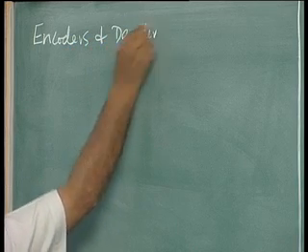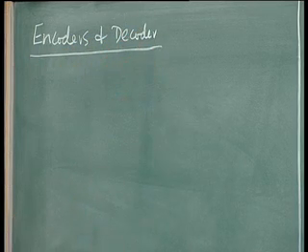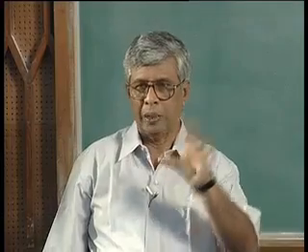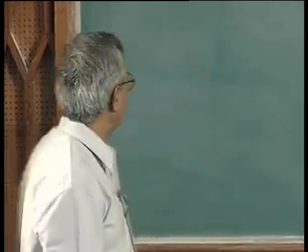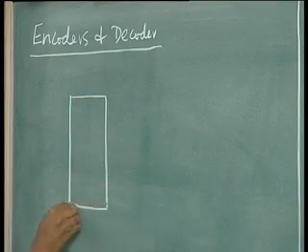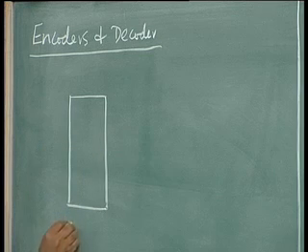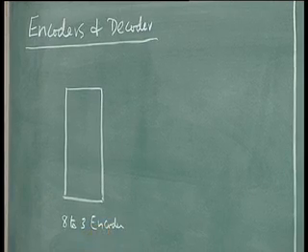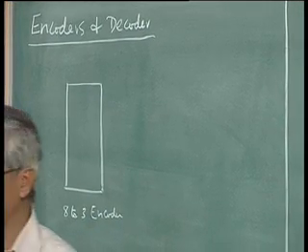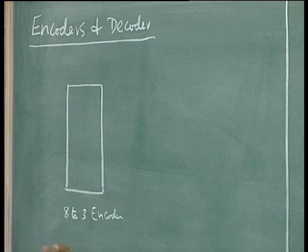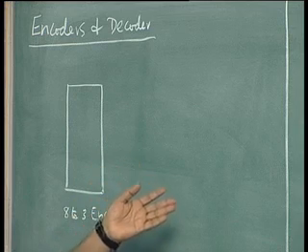As the name suggests, one codes the various combinations into a smaller number of bits, the other expands it back. So, an encoder, for example, suppose I had 8 inputs, an 8 to 3 encoder. Assuming only one of the inputs is active at a given time, could be active high or active low, all we have to know is which of these 8 inputs is active.